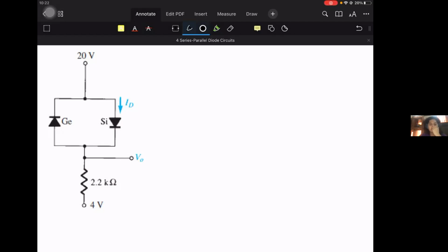So, rule of thumb, it adheres to our circuit laws. If we look at the sources, at the top is 20 volts, at the bottom 4 volts. Okay? For 20 volts, obviously its current flow is downward, for 4 volts it is upward. Now, the question: we could make this assumption and end up with the correct answer. But which of the two will be more powerful, which will overpower the other? So 20 volts, of course, since it is larger, will overpower 4 volts.